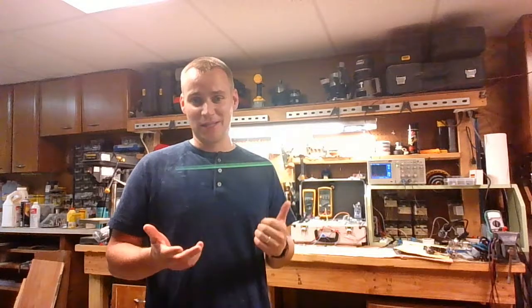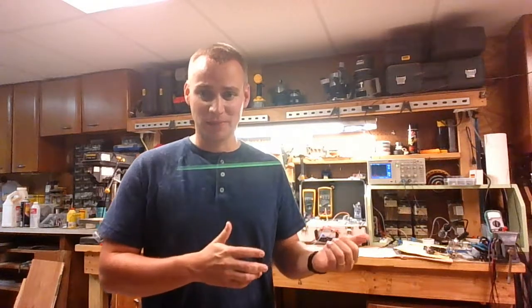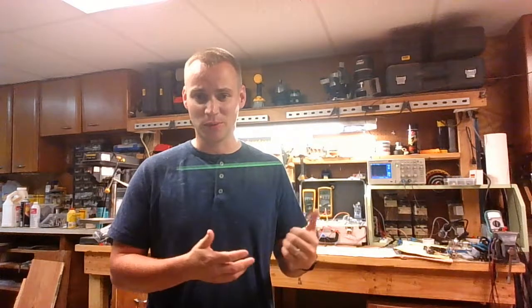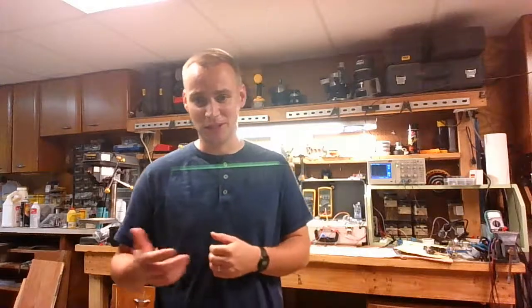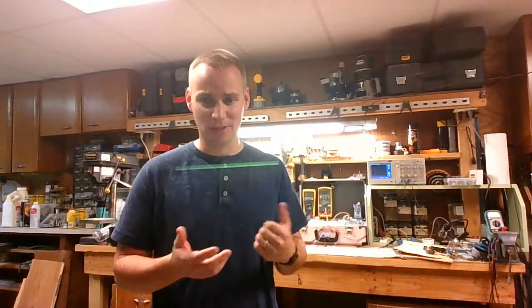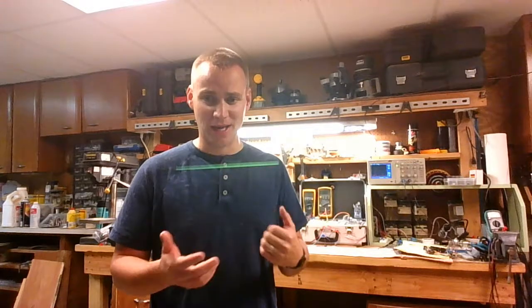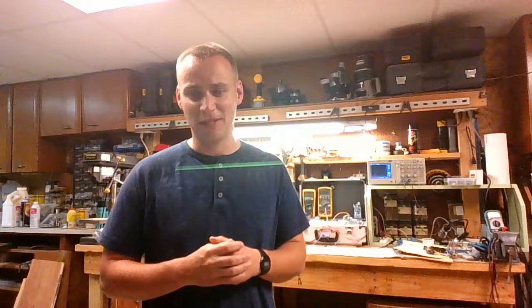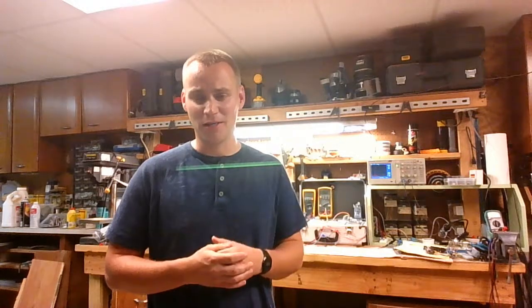We also want to analyze the current in terms of time. By this, we would monitor the startup current signature of each major appliance. We feel like loads such as water heaters will look different than loads such as a well or an air conditioner when they start up in terms of current amplitude. Pretty well the same as the FFT, but another way of monitoring and confirming what we've got with the FFT.